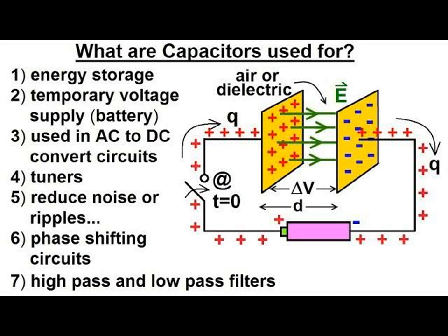So what we are saying is that the capacitance of a coaxial cylindrical capacitor is given by C equals 2 pi L epsilon naught all over ln B over A. The L is the length of the cylindrical capacitor. Good. Next is the A you see there, which is the radius of the internal capacitor. B is the radius of the external capacitor. The radius of the internal capacitor is always less than the radius of the external, while the radius of the external is less than the length of the cylindrical capacitor. You have to be very careful with those parameters because they are sacrosanct.